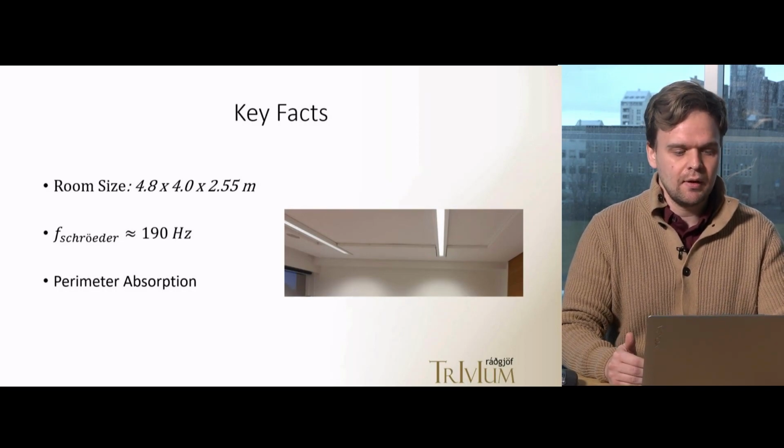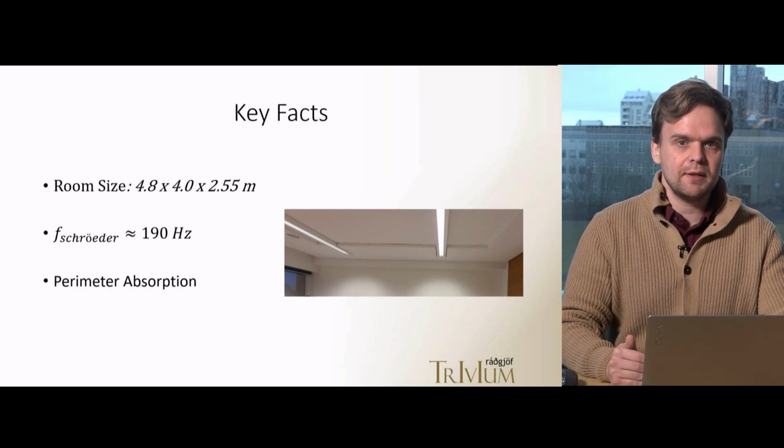that is, the frequency below which the modal behavior is theoretically dominant. Now, when I've been working with geometrical acoustical software, what I've usually started with is calculating the Schroeder frequency and multiplying it by a factor of, let's say, 2 or 3 or even 4 in some cases. I've estimated the frequency below which I do not usually trust geometrical solutions. Now, in this case, the Schroeder frequency being around 200 Hz would mean that I would never simulate this room using only geometrical methods. And therefore, being able to do this in Treble is very tempting.